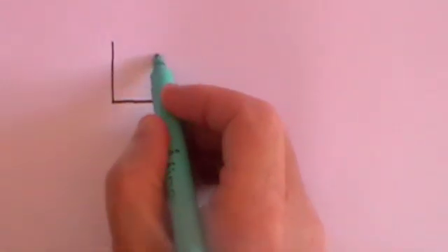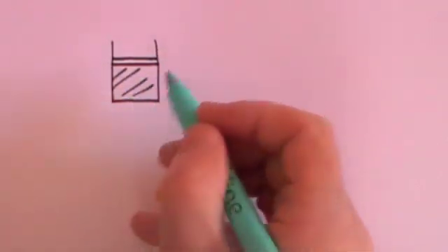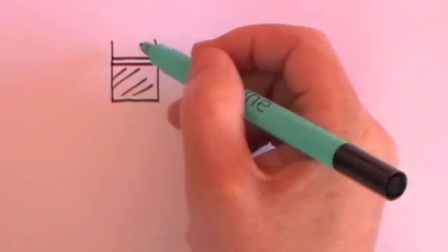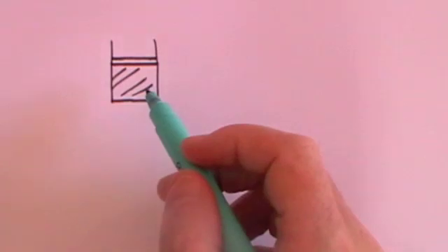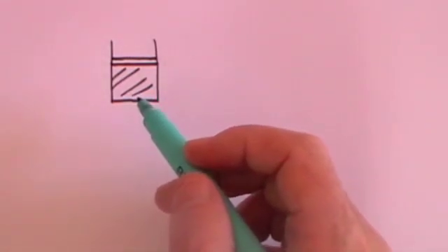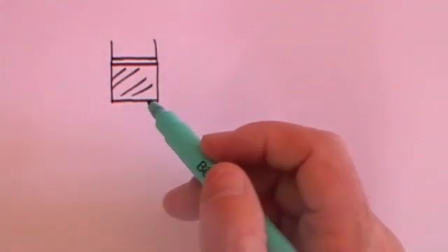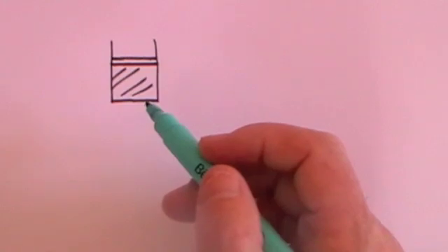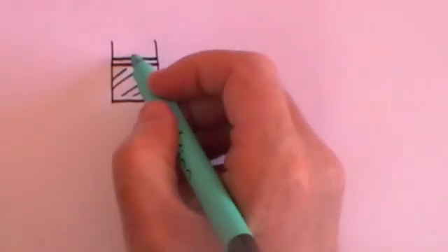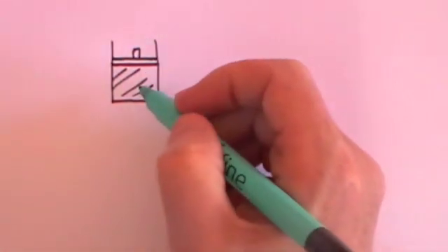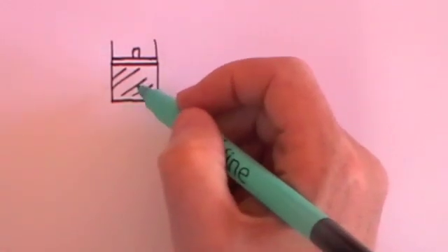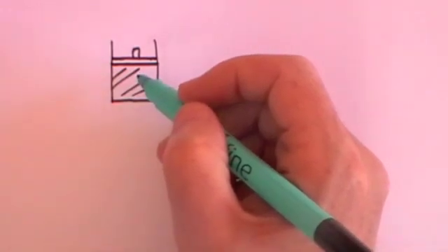Carnot went on to develop what is often called the Carnot engine, or sometimes the Carnot cycle. Basically it involves taking the gas that we had before with a piston, so the piston can slide up or down, either compressing or expanding the gas. And what you do is you change the gas sometimes adiabatically, which means no heat in or out, and sometimes isothermally, which means the temperature doesn't change. Now, if you are going to change it adiabatically, with no heat in or no heat out, then you have to do work, because that's the only way you can change it. In other words, you take hold of this plunger here, and you push it in, and if you push it in, the volume will go down, or you pull it out, and the volume will increase. Both of those are adiabatic changes, because no heat has gone in, and no heat has come out.